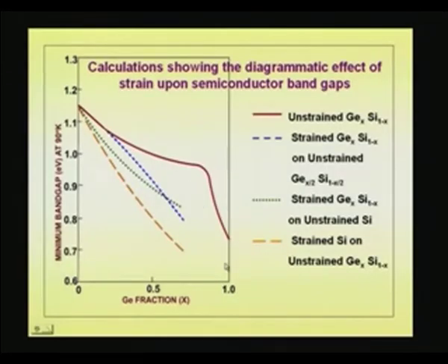The top curve: germanium 0.72, silicon slightly more than 1, in fact people talk of 1.11, 1.15, in that range. So, this curve shows it varying from about 1.15 to 0.72, and it all depends also on what temperature you are measuring at. But what we are talking of now is silicon germanium which is strained. The top layer is unstrained silicon germanium. When the layer is strained, the lattice is under stress and the energy band diagrams also undergo changes, and because of that you get a different band gap. In fact, you get a lower band gap.